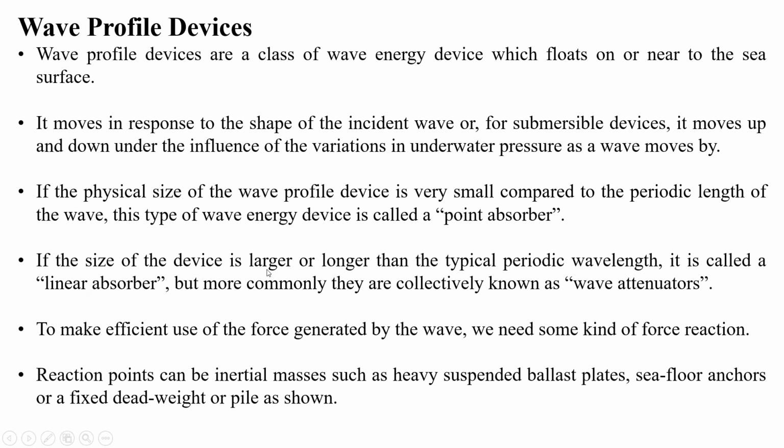If the size of the device is very large, or longer than the typical wavelength, it is called a linear absorber. So for very small devices, it is called a point absorber. For very long devices, it's called a linear absorber. To make efficient use of the force, generally we go for some force reaction.